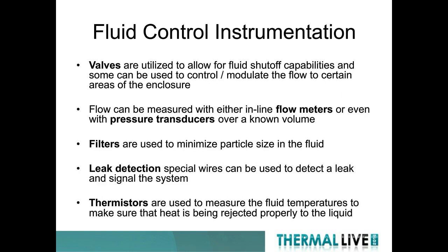For fluid control instrumentation, we see the use of valves. They're utilized to allow for fluid shutoff capabilities, and some can be used for control and modulating the flow to certain areas of the enclosure. Flow can be measured with either inline flow meters or even pressure transducers. If you know what a known volume is, you can make a calculation understanding what the pressure drop is under that known volume, and you can come up with the flow rate.